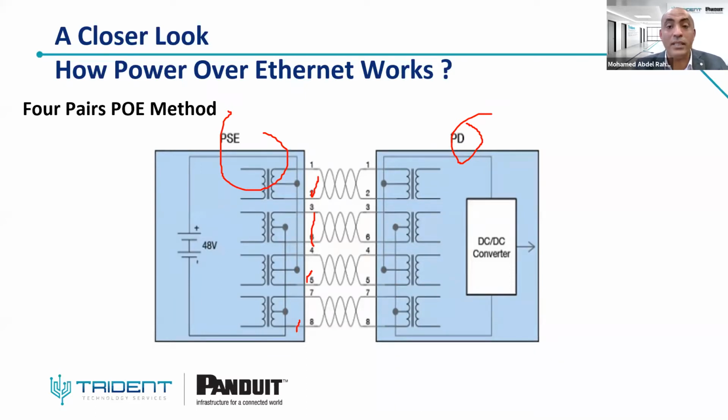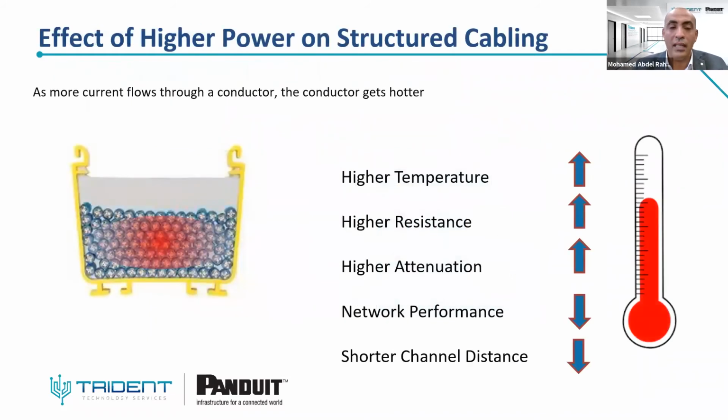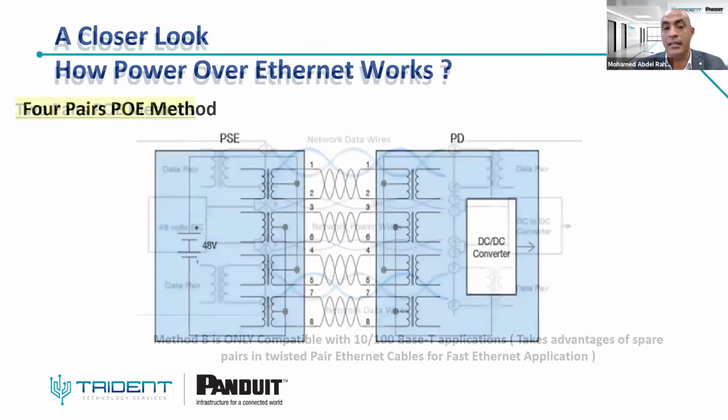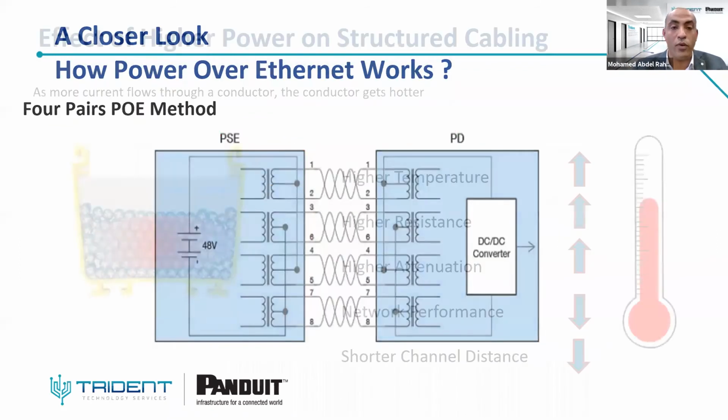As discussed before, the DC resistance for each conductor is very important. We need to have balance between each conductor. Any difference between the resistance of the conductors will result in higher DC resistance imbalance, which will cause errors, retransmissions or bit error rate issues. We will also discuss this issue during the topic of testing.